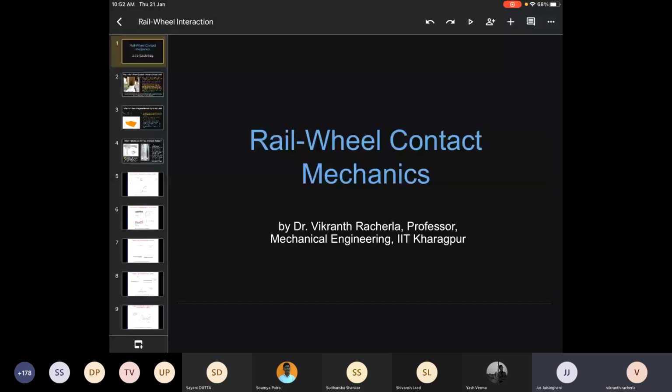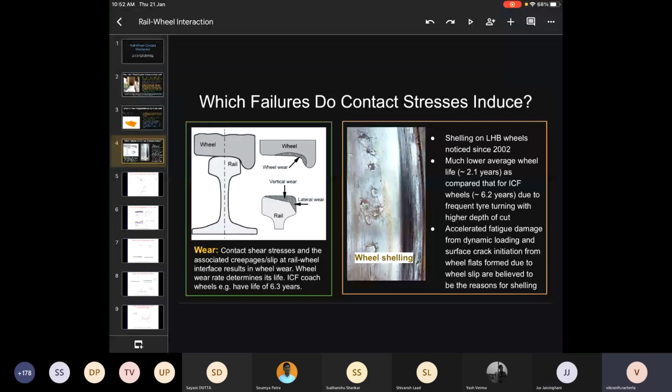By rolling contact here, do we mean the spherical or the cylindrical one? It is normally neither. It is basically contact between two bodies. Many bodies are neither spherical nor cylindrical. Spherical and cylindrical are chosen because the analytical expressions are simple. Take this rail wheel example, where you have two sets of curvatures.